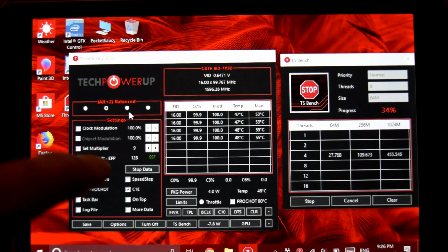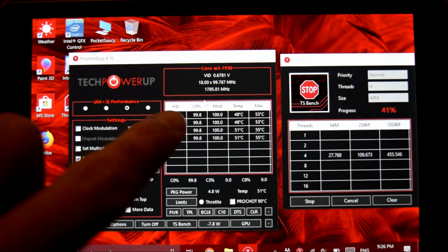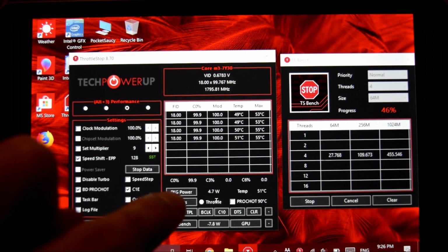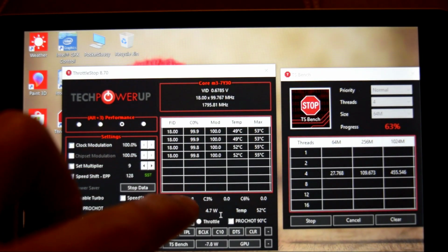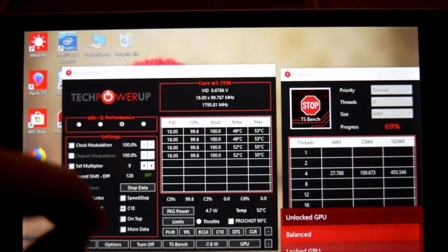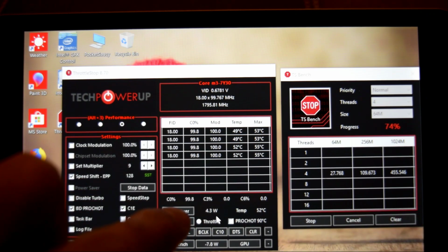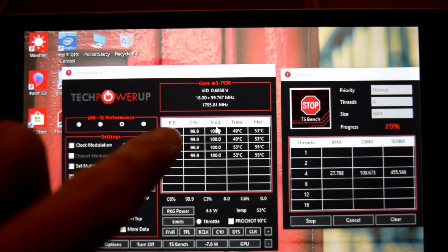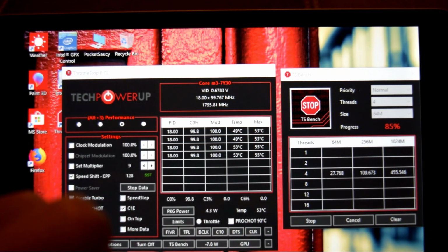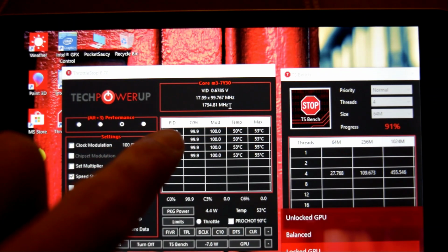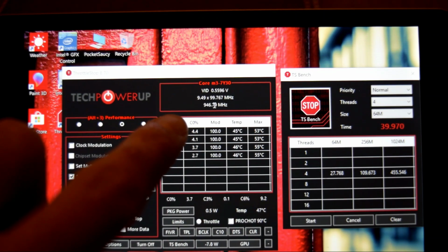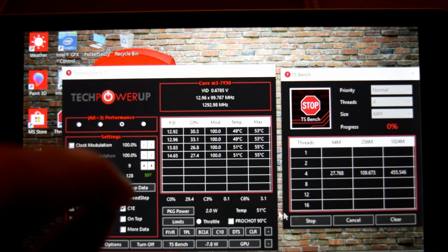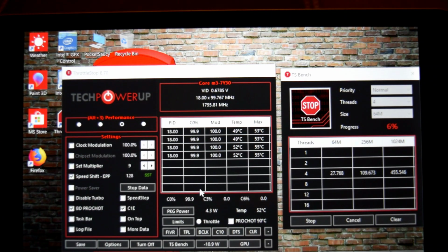Now watch what happens when I raise it to 1.8 gigahertz. All of a sudden I can hold it with 4.7, whereas it shouldn't happen like this. This is still too close. 4.3 gigahertz, as you can see when I put it on the conservative profile. Now the GPU is not taking any power. Everything's going to the CPU, 4.4, and I'm at 1.8 gigahertz almost. This is exactly why you want to undervolt, because you can get more out of doing less.